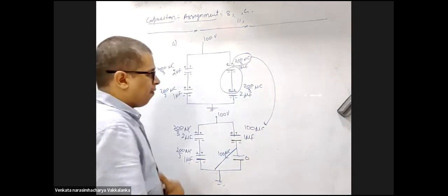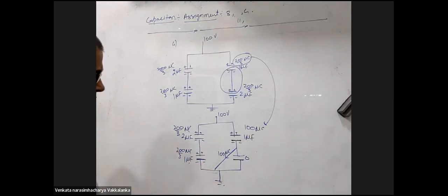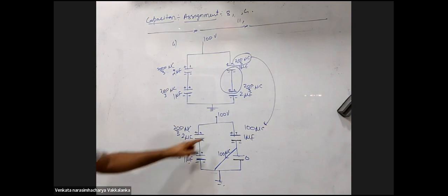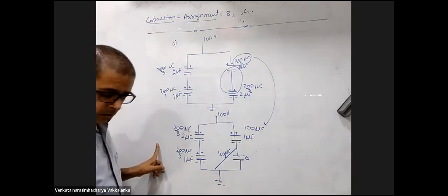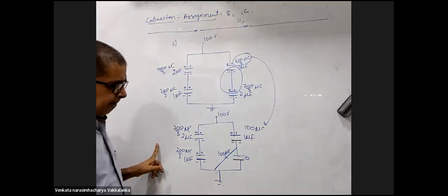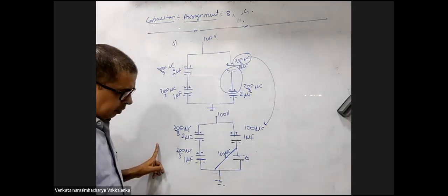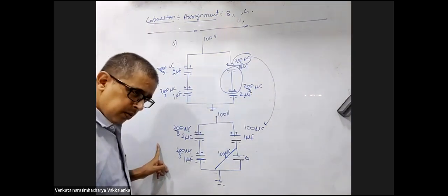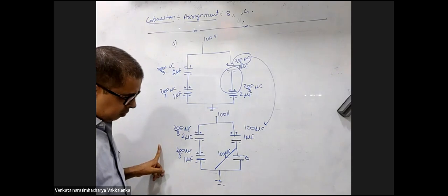In the diagram you have made below, over here, let's say there was a 100-volt battery connected to the left of this, just for 1 second. Yes, there is a 100-volt source over here. So now the net entire charge on the capacitor system should have been 500 by 3, because 2 by 3 plus 1 is 5 by 3 and potential difference is 100. So in total, the splitting of the charges should also give us total charge as 500 by 3, right?